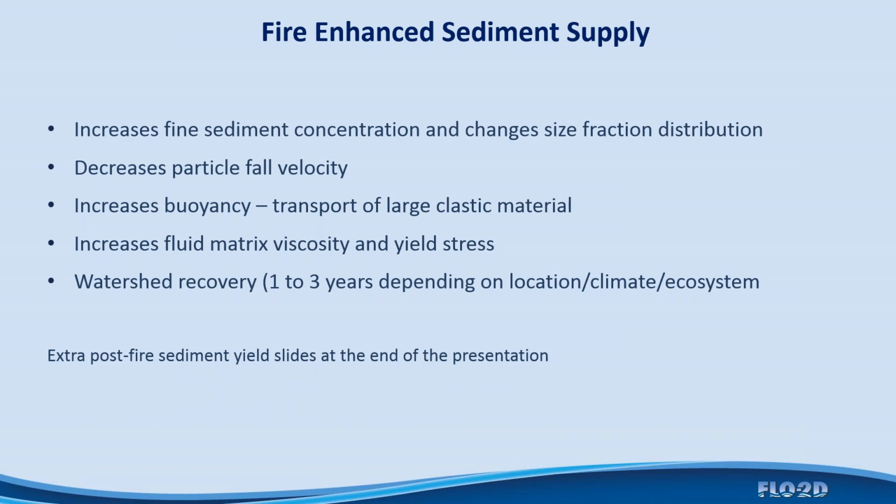This will change the size fraction distribution that might be in the bed, and this causes a decrease in the particle fall velocity and an increase in the buoyancy, so you can transport more larger boulders and so forth. It increases the fines when you load it, and some of this might be organic loading too, and the fine material, the ash and so forth, will increase the fluid matrix viscosity and the concurrent yield stress too.